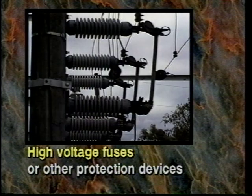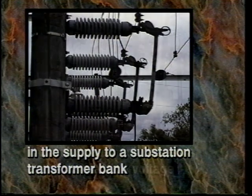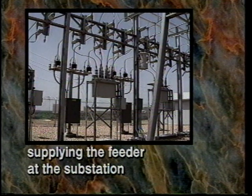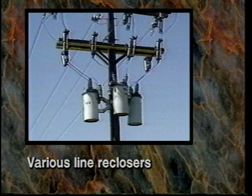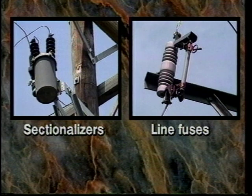This includes high voltage fuses or other protection devices in the supply to a substation transformer bank, a circuit breaker or reclosers at the distribution voltage supplying the feeder at the substation, various line reclosers, sectionalizers, line fuses, the wire arc burn down characteristics at the fault location, ground resistance, etc.